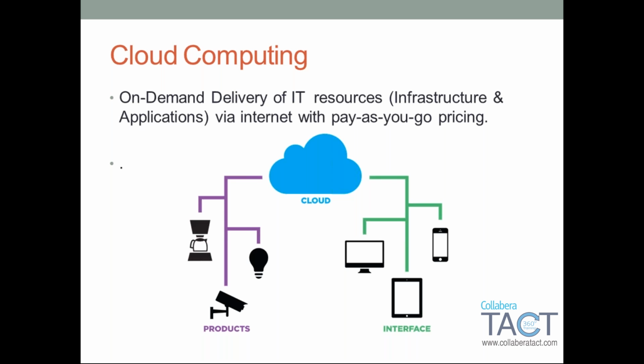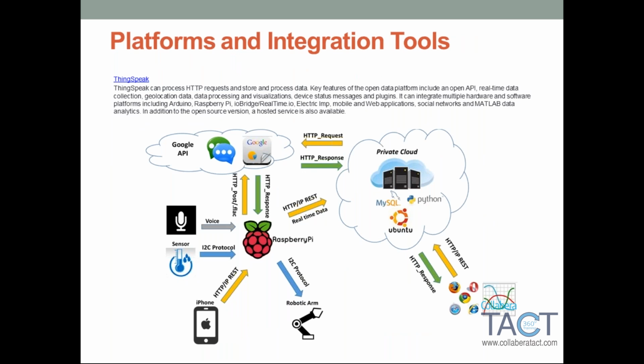Now, moving to the next slide, this slide shows a complete implementation of an IoT-enabled system. As you can see here, the end devices are running on 8-bit microcontrollers. The Arduino platform is one very good example of 8-bit microcontrollers. Most end devices run on 8-bit microcontrollers for the same reason, to reduce power consumption, because these end devices are not going to manage a lot of computing work. Their job is just to collect data, send it to the cloud, and generate mechanical actions when a signal comes from the cloud or from the end user.